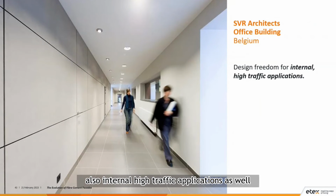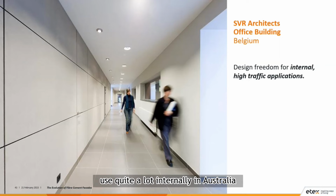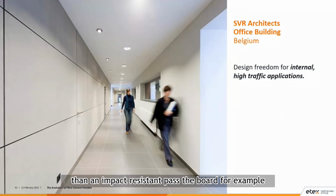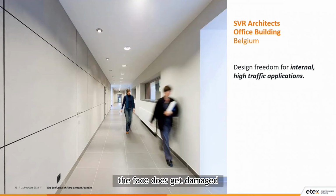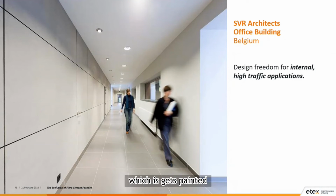Also internal high traffic applications as well. I know EQUITONE's used quite a lot internally in Australia. And because of the high density nature of the panel, it will take impact a lot better than an impact resistant plasterboard, for example. And with our panels like our Tectiva panel, which has the same color running all the way throughout, if the face does get damaged, you still have got the color running throughout the panel. So it differs from a high impact plasterboard, which gets painted, and if the wall gets damaged, you will see that plaster behind.